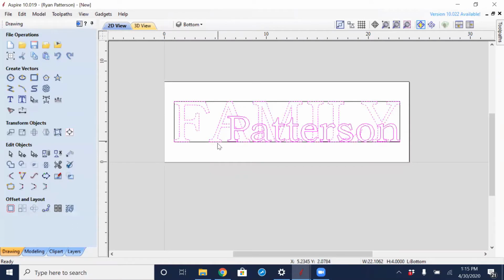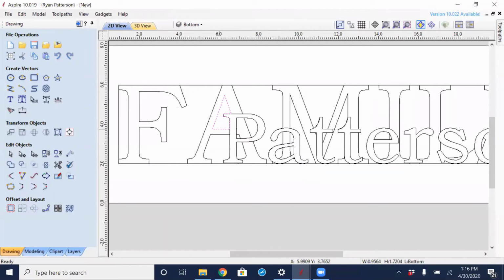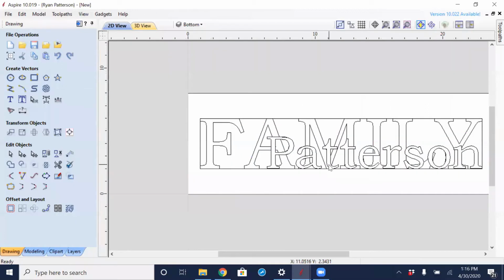Now select that and ungroup. And just to point out, it does show our layers and levels. When you're wondering what layer an object is on, select the object and, in the bottom right, along with the width and the height, it gives the size or the layer name. So we're able to see that they are separate. I just wanted to confirm that I was still on separate layers after grouping and ungrouping, to make sure they didn't all get put onto the same layer through that process.